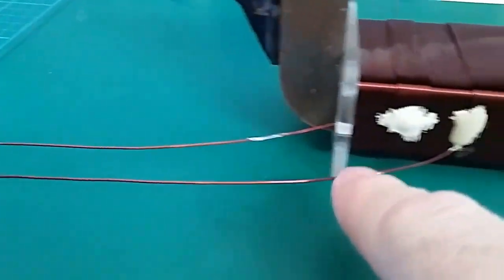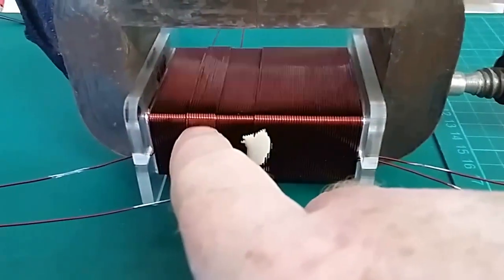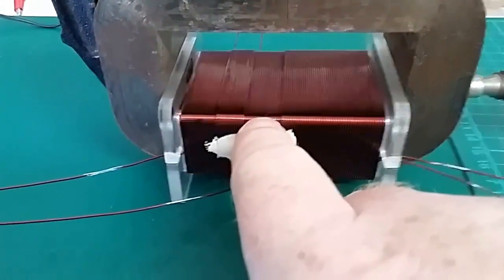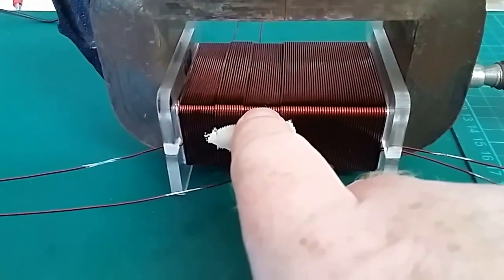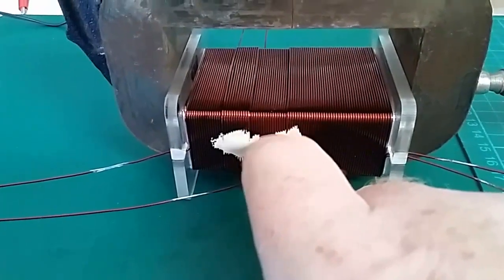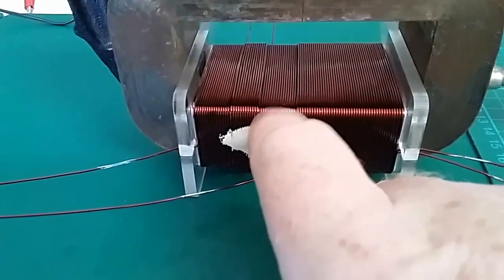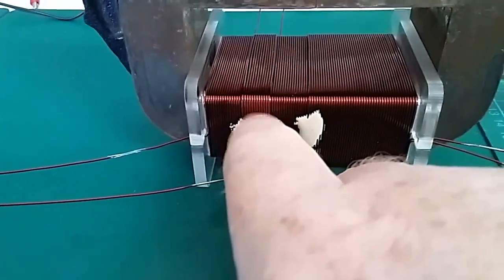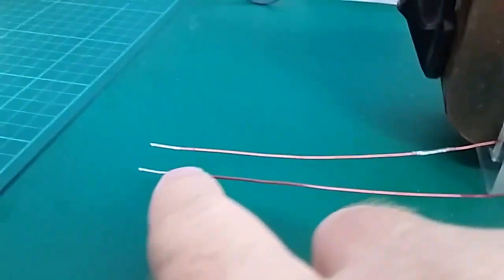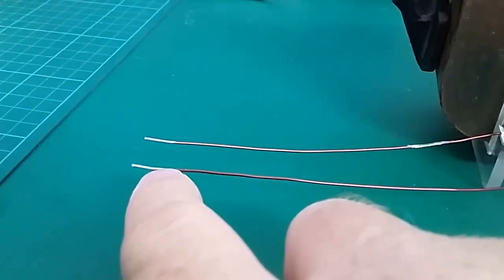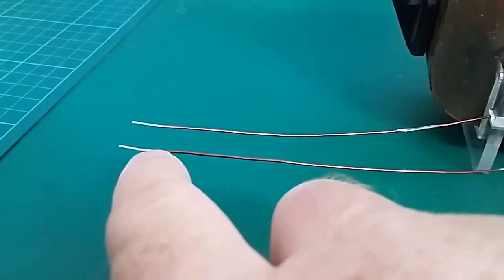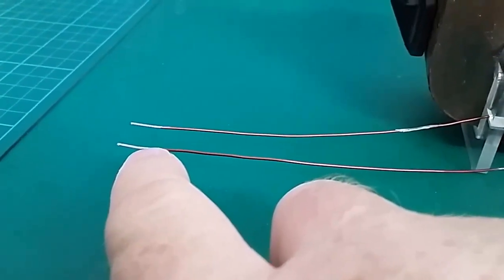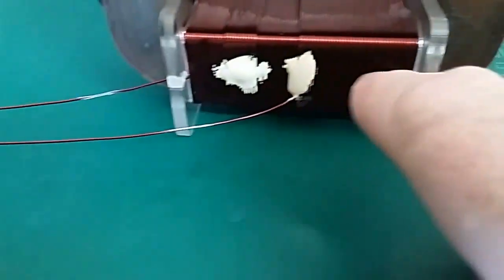the current won't flow. Okay, so what we found in the last experiment was that our 12 turns here compared to our 45 turns, which is a 3.75 turn ratio, so we've got 3.75 more turns on this half of the coil from this bit here all the way back to this bit here, wasn't enough to get the voltage up. Our voltage stalled, if you like. We couldn't get it any higher than what it was.